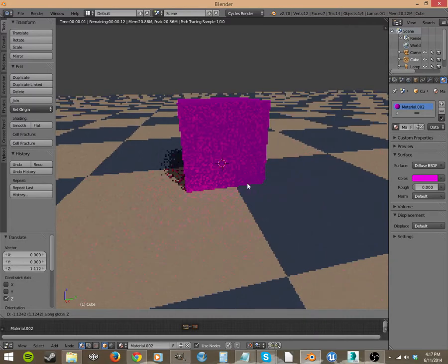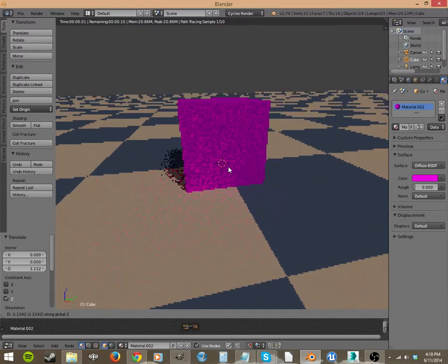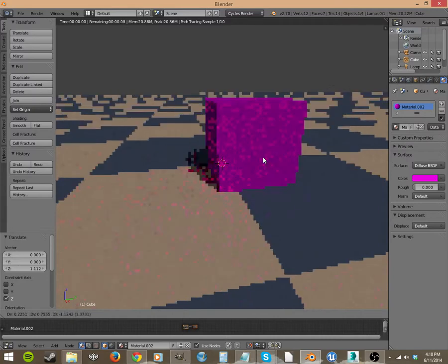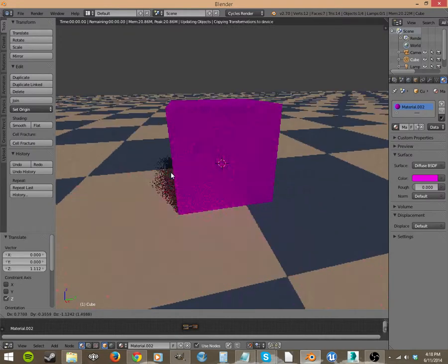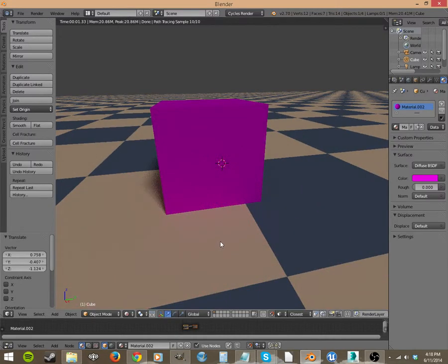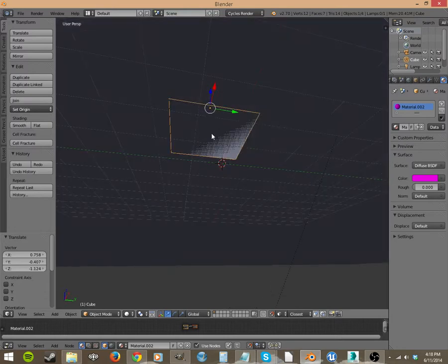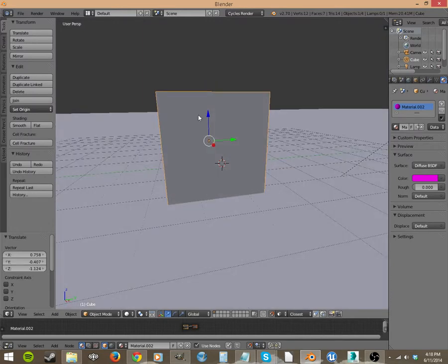we can lock it to the Z, and it's just gonna move it straight down. See, I can't move it up or down any further because it's snapping to it, and it's locked to the Z axis. If I turn that off, now I can move it around, but it's always gonna stay on this plane. It's just snapped right to it. Really great way to place things right on. You can see those two faces are sharing a space. That's why they're shimmering like that. Really great way to set things right on another surface.